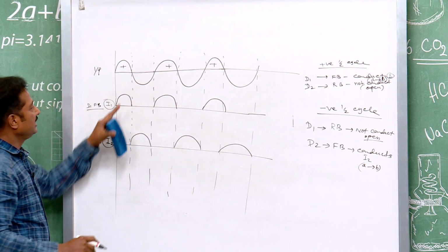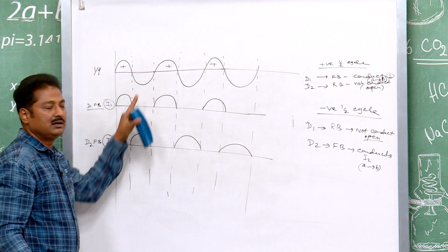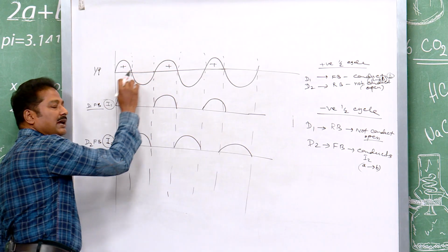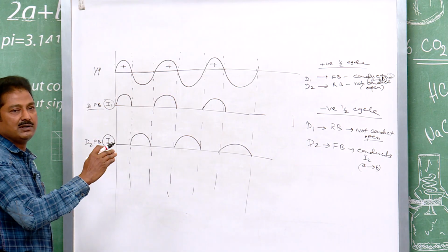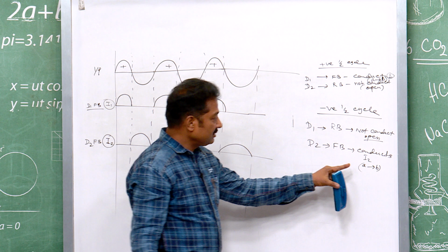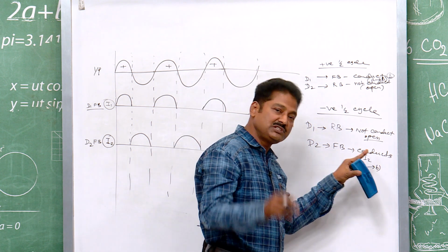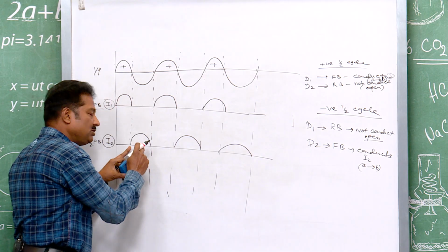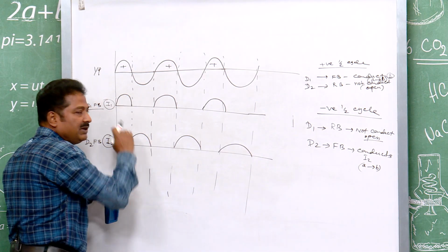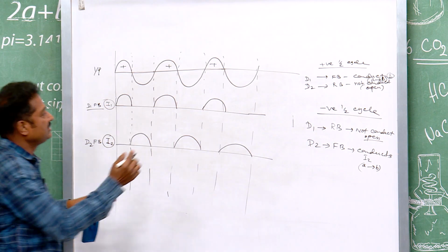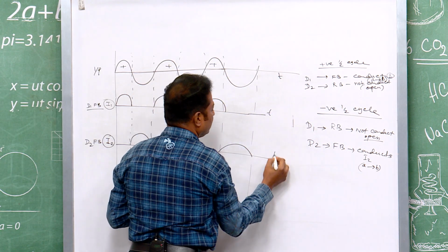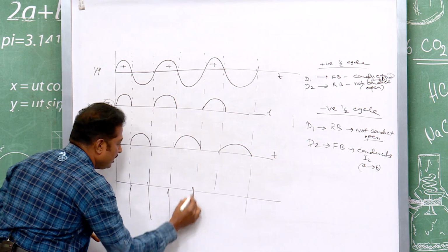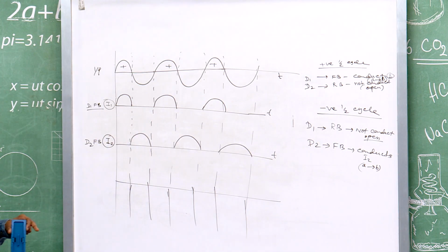And you see the negative half cycle is inverted, but it is erect, because the input negative half cycle direction was from right to left. But in our rectifier, it was still A to B. I1 was from A to B, this one also A to B. So, all will be above the x axis, or above the time axis. These are the time. So, now you add all the cycles, all the half cycles.